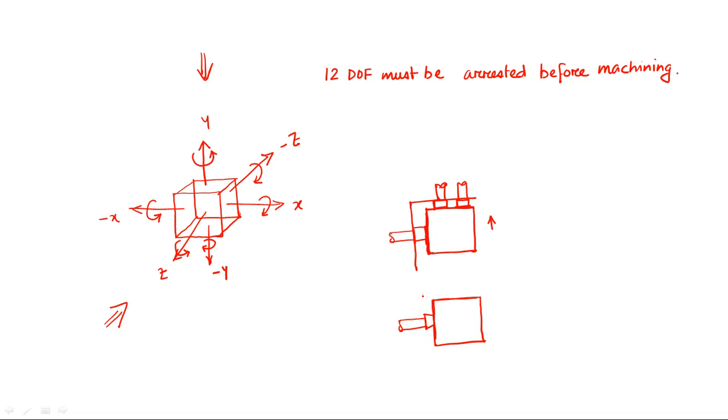Now always remember that whenever we have to provide support to any flat surface, we will always use 3 pins, and these 3 pins will be fixed type. Fixed type means it cannot be adjusted. So these pins that can be seen in the top view can be shown in the front view like this.